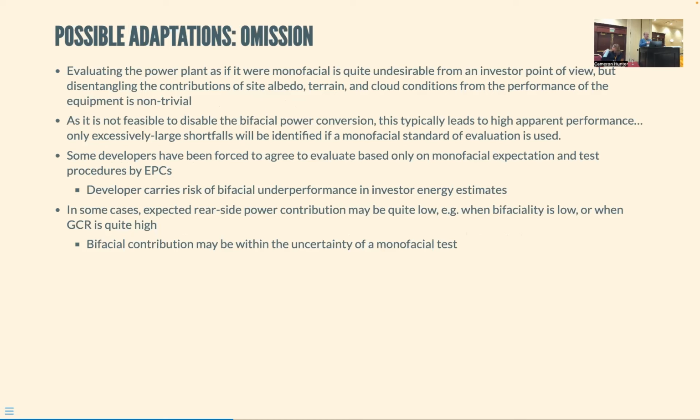So one way to deal with this is to pull out your hair and say, ignore it. I'm just going to test this with a standard ASTM test that only looks at the front side irradiance. What'll usually happen then is that you'll have an expectation that less power is going to come out because you modeled it as monofacial, and more power is in fact going to come out because it is bifacial, and the EPC is going to be happy because they get more power out and pass the test 99.99% of the time.